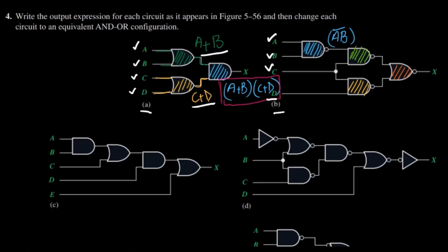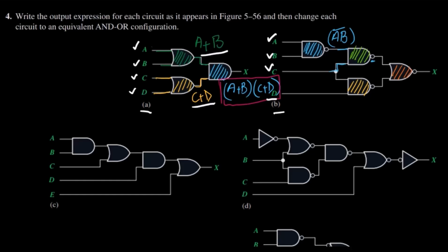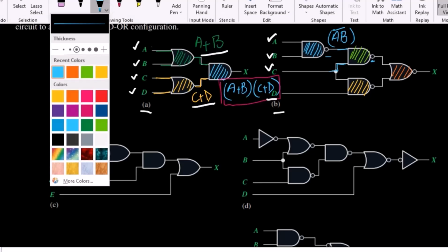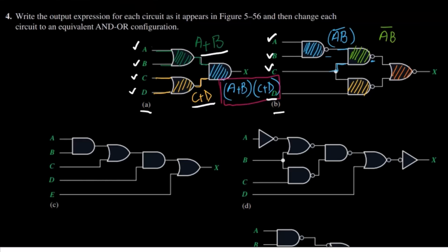Similarly, this is now applied here, and with it this signal, C, is also applied here. At the output of it, this is another NAND gate, because of this bubble here. So at the output of it, what will I get? Let me draw it again here, with this light green. AB whole complement multiplied by C, and the whole complement. At the output, we will get this signal.